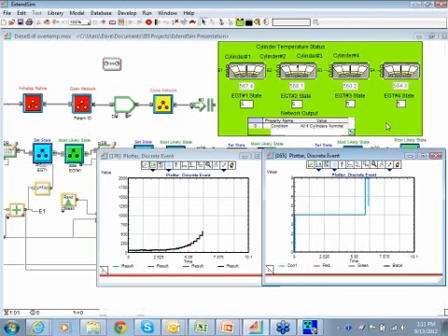Okay, you notice on the graph we got a transient there where we actually went to state 8 as we went to normal operating temperature. And now I've got a fault in there where you can see that cylinder number 4 actually ran to an overtemp condition. So it's gone to a different state of high. So it's just going to run to the conclusion here.